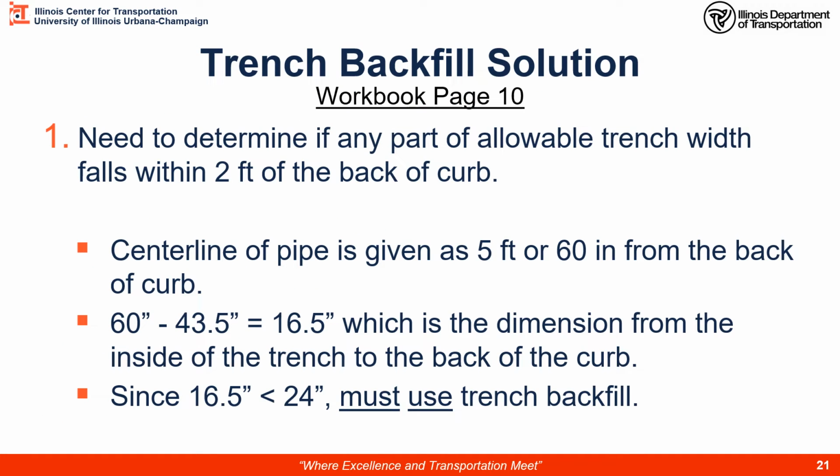So a little more formal, here's our solution. First, we're going to do that check to see if we do need to pay. And indeed, when we do our calculation, 5 feet, 60 inches, minus the 43.5, is 16.5. Yes, it is within the 24 inches, so we must use trench backfill.